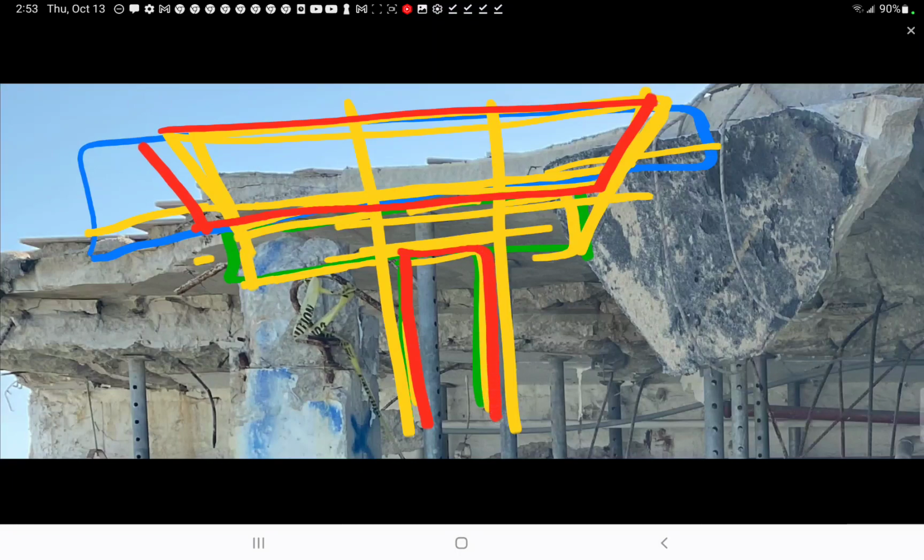Now remember, the wire's at the bottom of this. As you put your next column over here, same thing and same effect. But between the two, the wire at the bottom acts as bottom steel. And it keeps that deck flattish. As you load the top, it keeps it flattish. Of course, the deck below also has to stop some of that deflection. It helps in stopping some of the deflection.